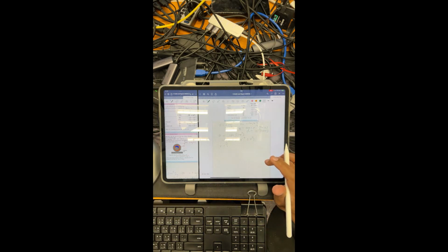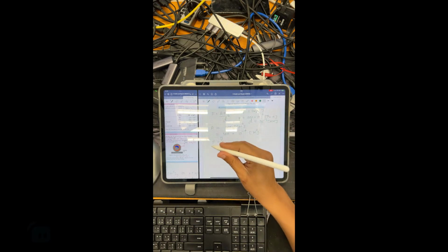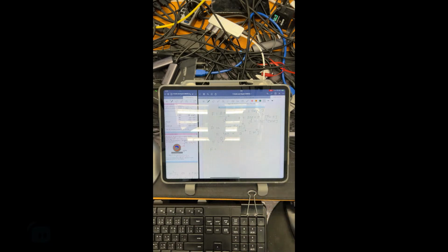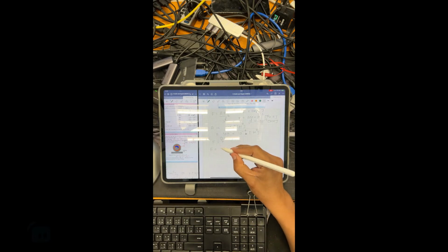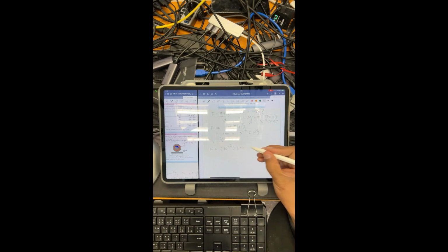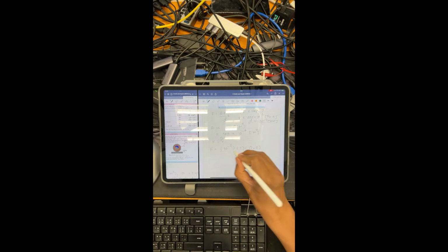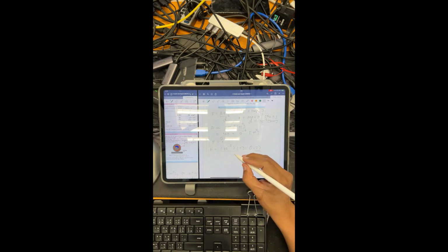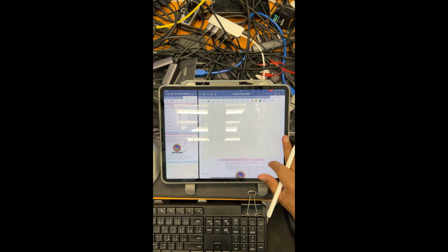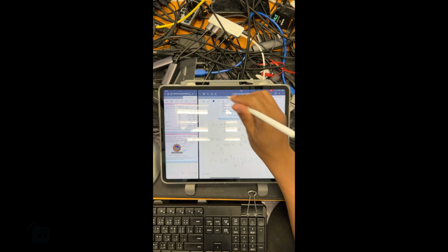All right, so we will substitute everything into that formula. F is equal to A, which is 10 to the negative 2, right? And V is velocity 1 meter per second, and eta is 0.2, divided by the distance d, which is 10 to the negative 3. 1 millimeter is 10 to the negative 3 meter, right?